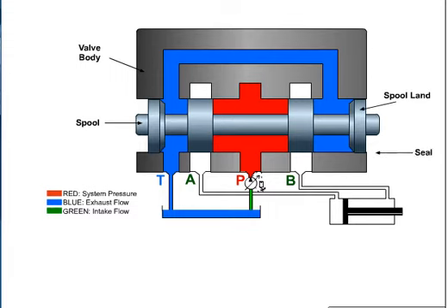Directional spool valves are sealed along the clearance between the moving spool land and the housing. The degree of sealing depends on the clearance, the viscosity of the fluid, and the pressure. Because of this slight leakage, spool-type directional valves cannot alone hydraulically lock the actuator.